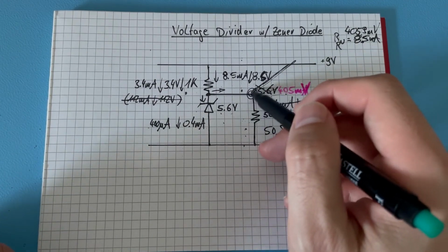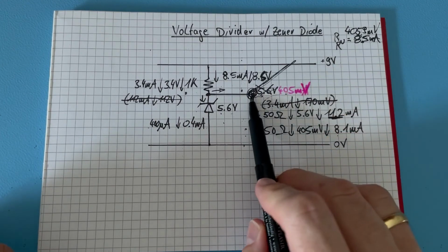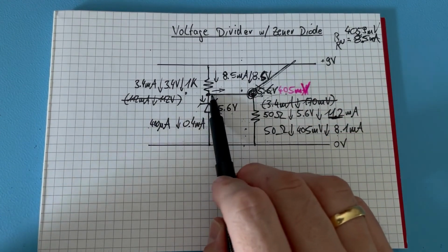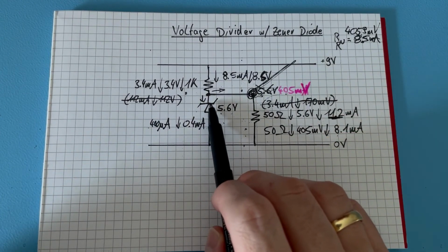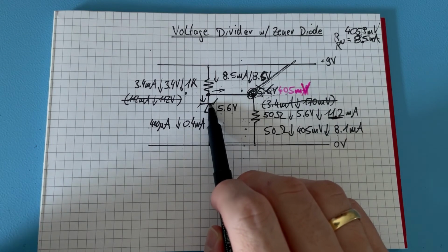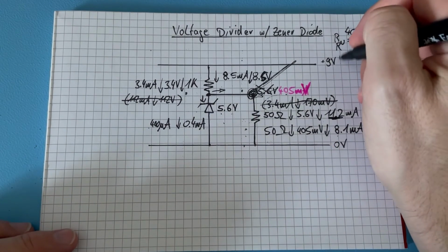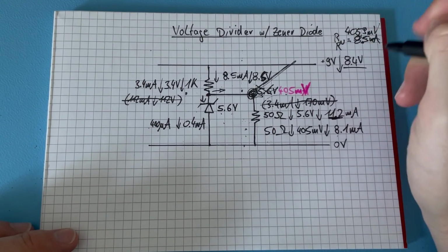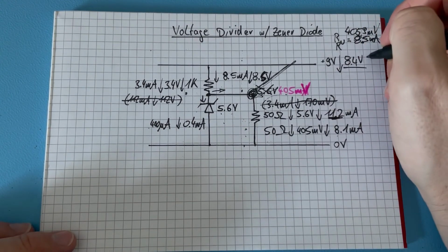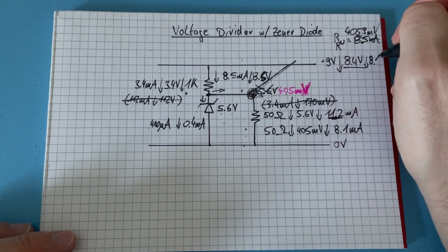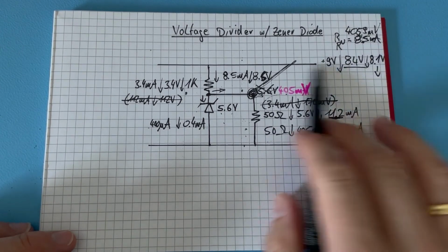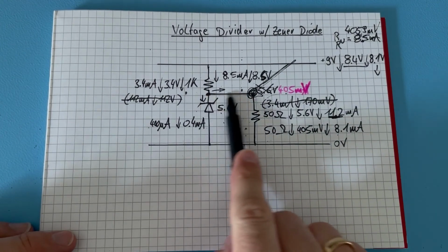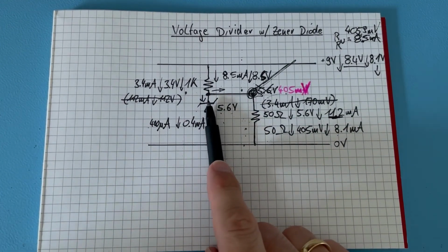When there is a transistor sitting here, we've seen that already. Then the Zener has the property that if I go lower here on the 9 volts, so perhaps I've seen 8.4 volt, for example, on my batteries, or you can even go down to, I don't know, 8.1 volt or even lower, then the Zener has the property of keeping the voltage here stable. And that is a very cool thing.